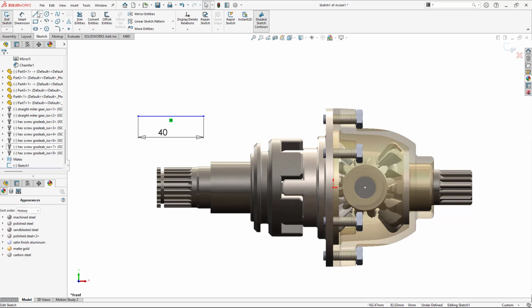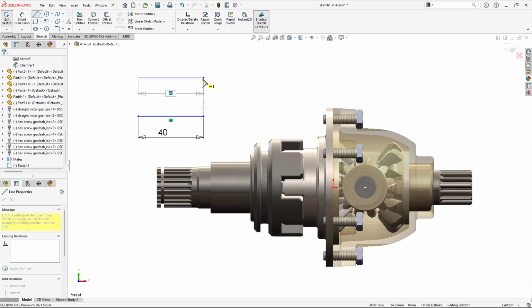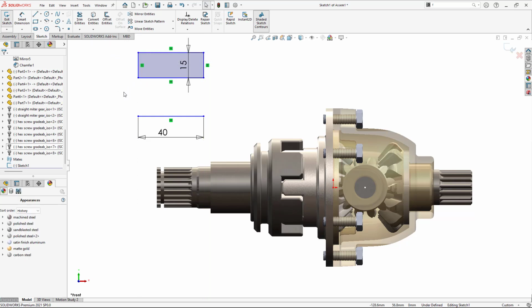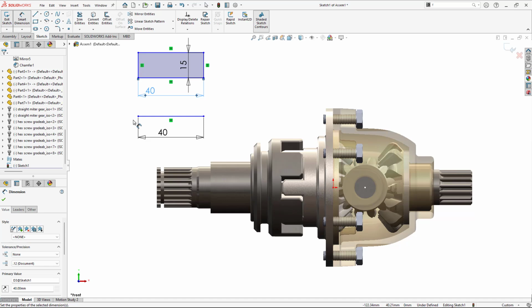And now if you would like to create a sketch again, you can see you have the direct on-screen numeric input as active. You can enter the values as per your need. If you don't want to have the values, you can simply click so that it will automatically create without dimensions. So these are the two important settings we should have.